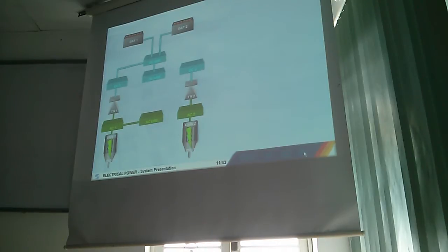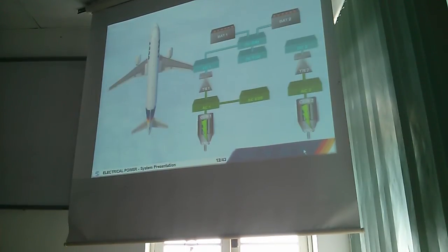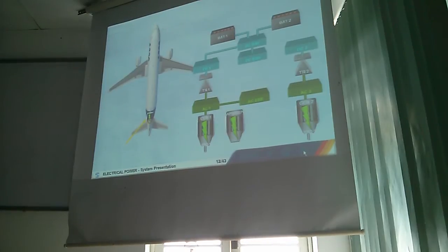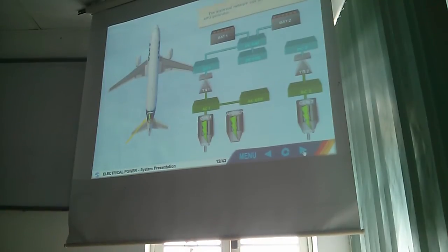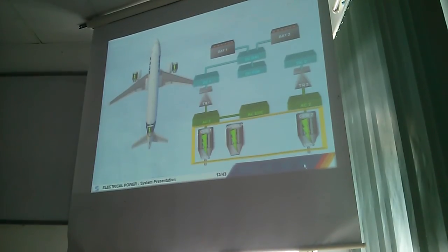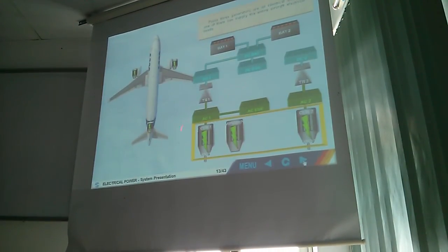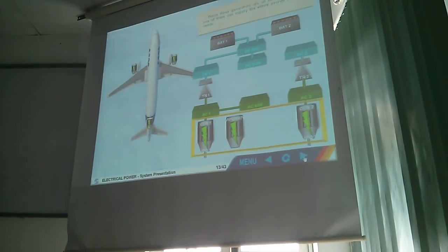We will now introduce some other components which supply the basic system. The electrical network can also be supplied by the APU generator. These three generators are all identical, and any one of them can supply the entire aircraft electrical needs. No IDG on the APU, because the APU is turning always at the constant speed, 100%.